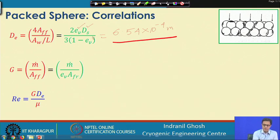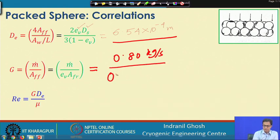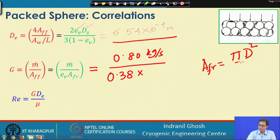Once we know the equivalent diameter, we come to the mass velocity part, where the mass flow rate is 0.80 kg per second. Then the porosity has been given as 0.38, and the frontal area, obviously, is pi d square by 4.